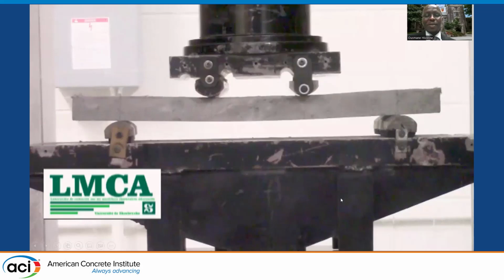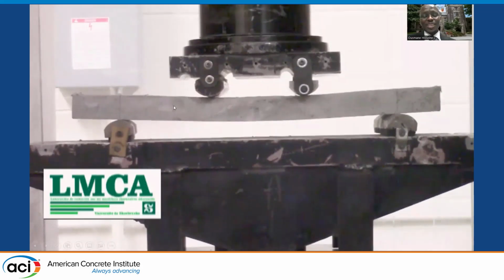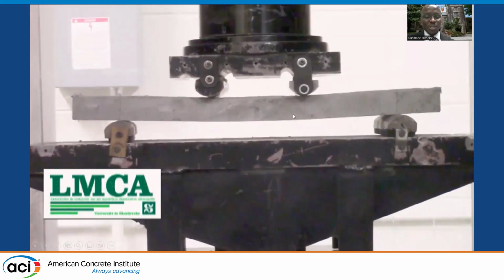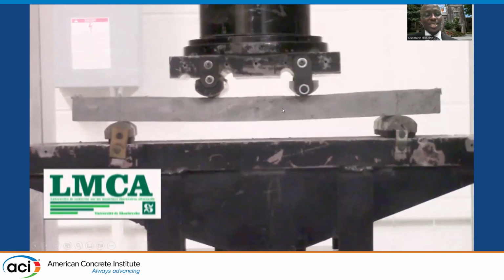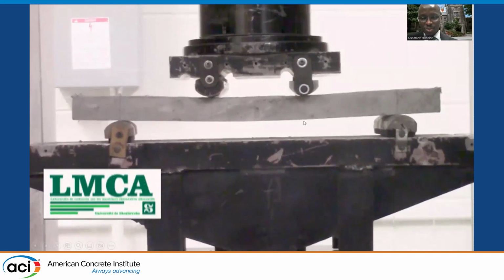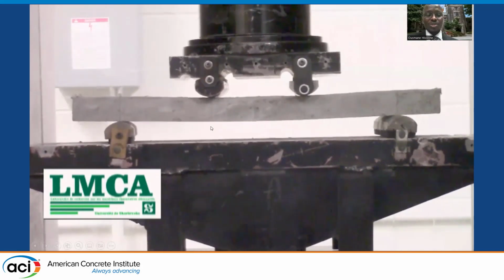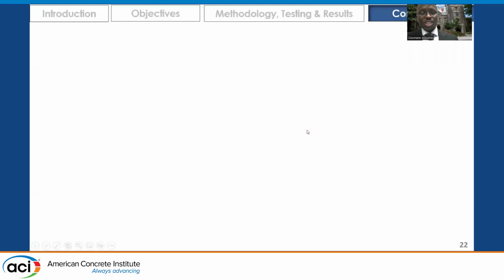At the flexural testing scale, you could see here that these systems can show a ductile-like behavior after several repeated excitations, even after cracking, by the way. Under these supports, in-person observations showed significant cracking appearing, especially at these supports, but at this load application point, the resistance will change.